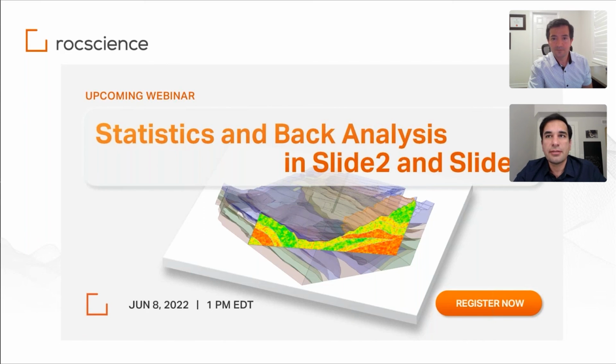The next question is, are there any direct correlations with CPT results? There are direct correlations between CPT and the in situ state parameter, and it is an integral part of any analysis, especially in tailings dams analyses. That's the first thing you would do. You would interpret the state parameter in situ. You would deal with the variability of the state parameter the same way you would do the characterization of any site. Plewes et al. 1992 is currently my favorite method for doing interpretation of the state parameter.